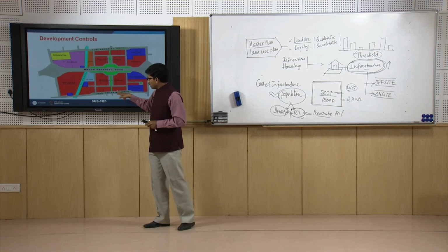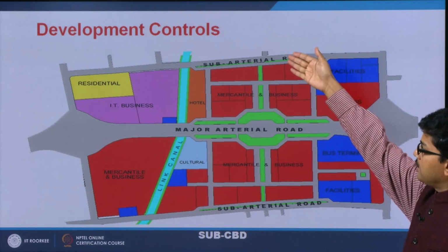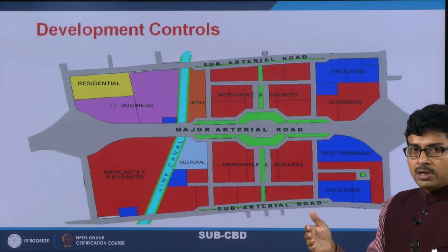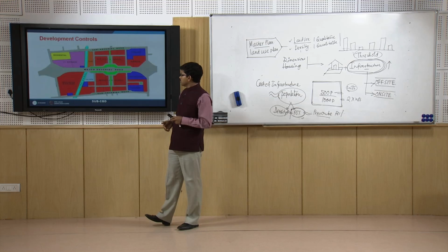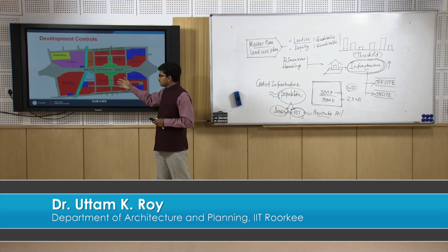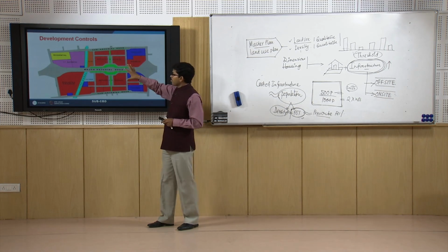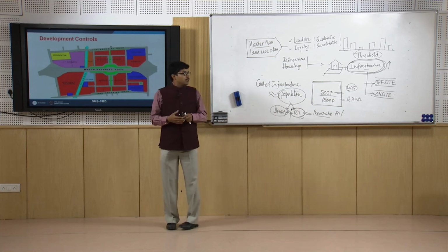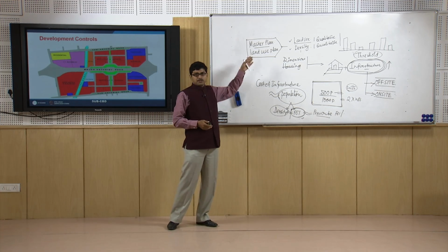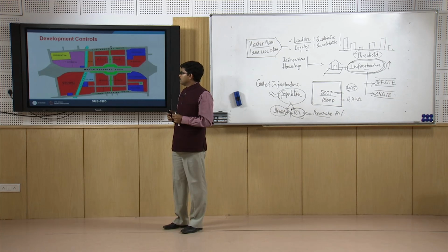You can see how the road is widened based on the requirement here and in other areas to accommodate parking and other facilities, so that we can have a few other off-site infrastructure and facilities which are not there inside the plot. So inside the plot and outside the plot are both required. This kind of exercise is required to be done after the master planning exercise, so that we can define the buildability and the envelope of the building.